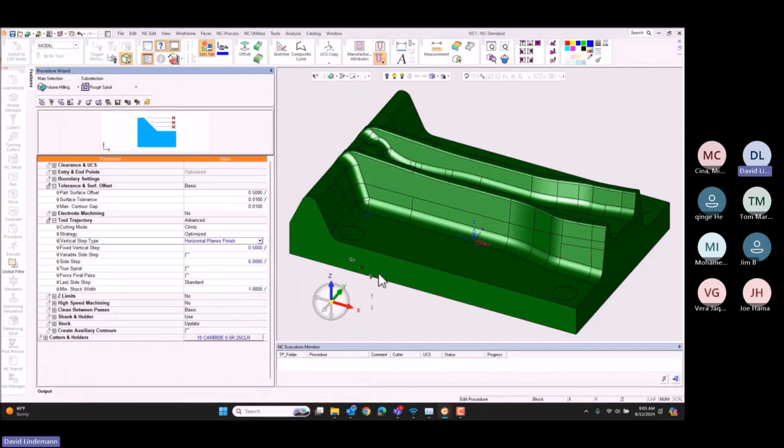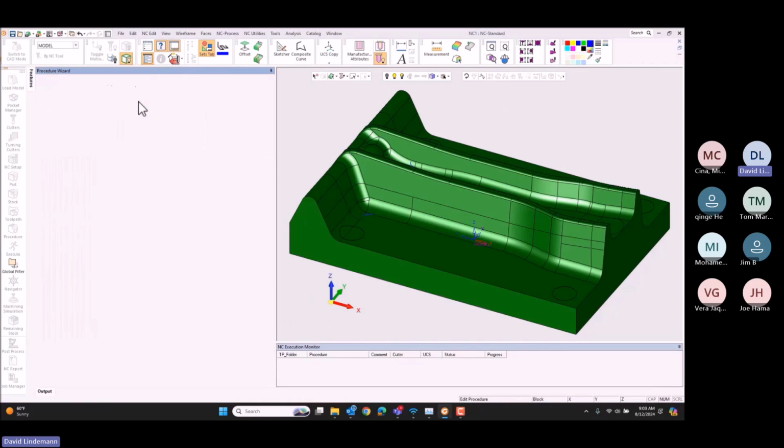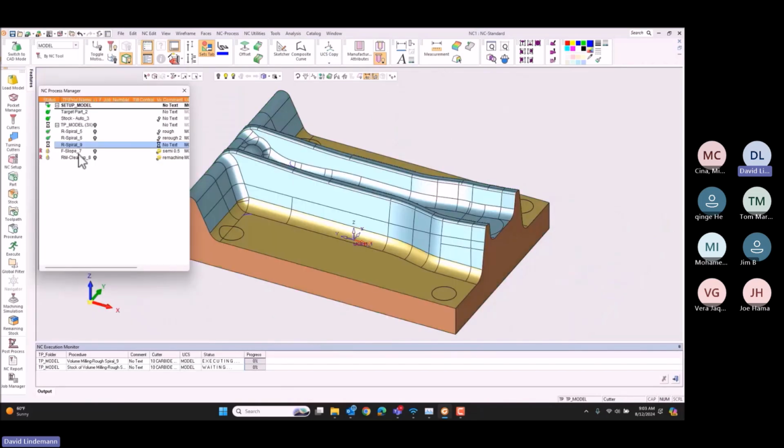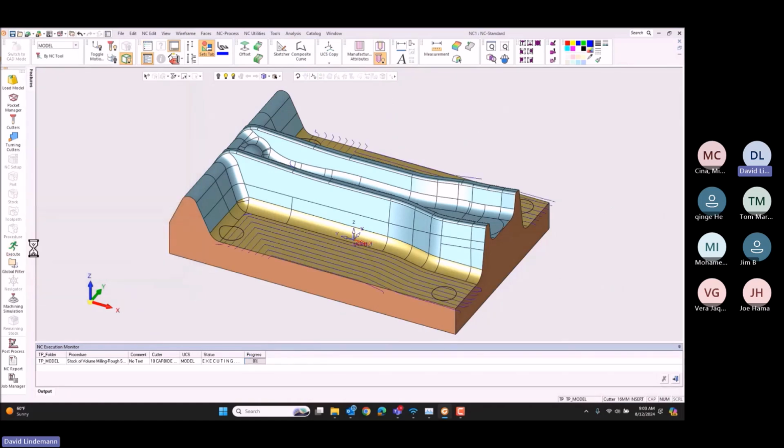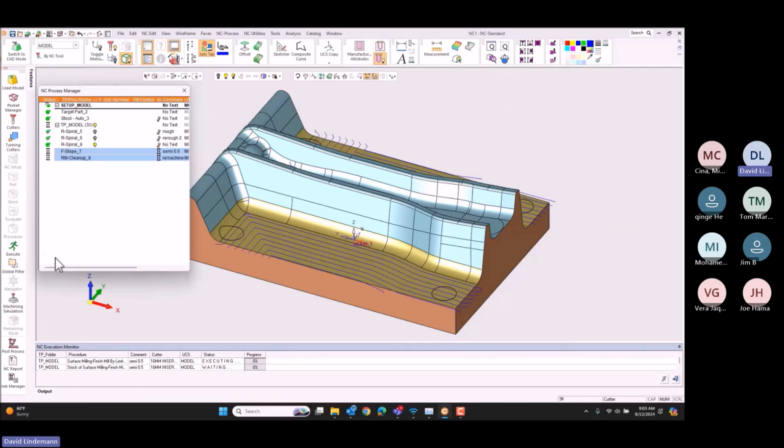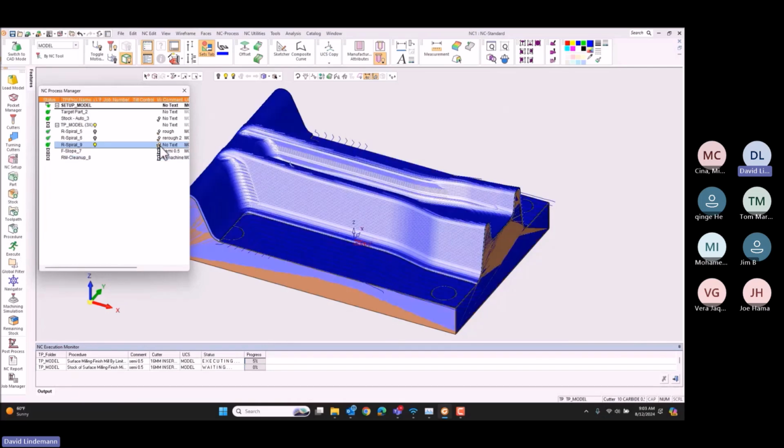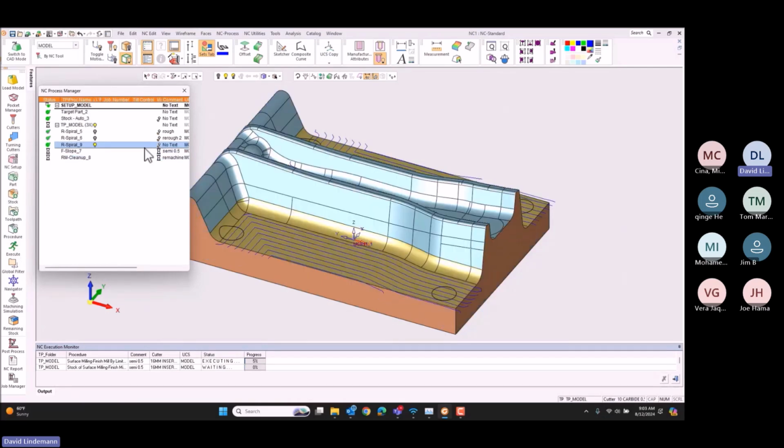So again, we've got different ways of cutting with standard, climb cutting, keeping everything optimized for tool retracts. And because I put that floor cut in before I did the sidewalls, you see in the sequence of events there, it's asking me now to recalculate those previous toolpaths. Okay. And it makes sense because it knows the stock changed.